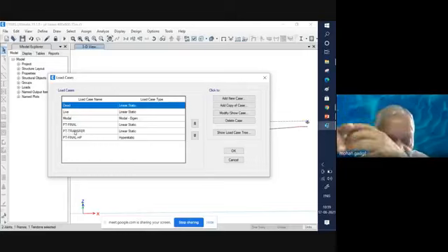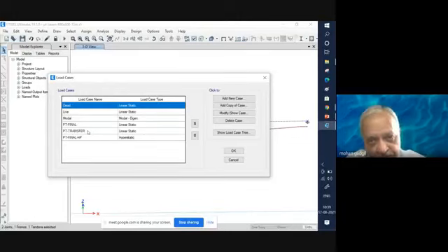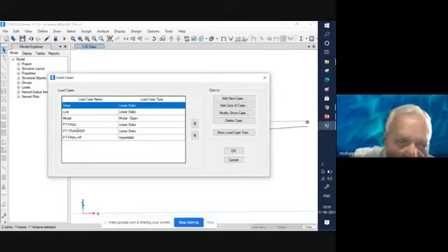Initially it has only the self weight. So for self weight only, you need to consider PT transfer, because the losses are yet to occur. PT is the pre-stressing force at the instant when you stress the cable and lock it; whatever force is transferred to concrete at that stage is called PT transfer.